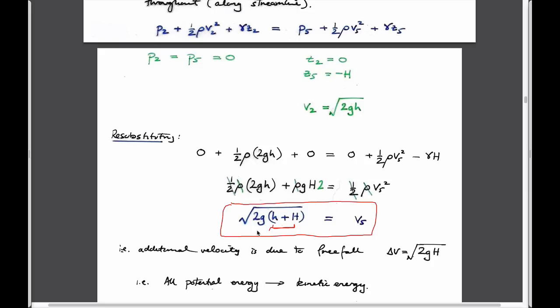And so the other interesting thing that we could surmise about that, which is one of the reasons that we took our jet lev condition to be simpler, is that you see from this that clearly V5 is greater than V2. Not surprising. It's actually the same as if the water comes out going at this velocity and accelerates just like dropping something down. So it's no different from dropping something onto the ground. It's the same as a weight that's traveling downwards. It just happens to be liquid.